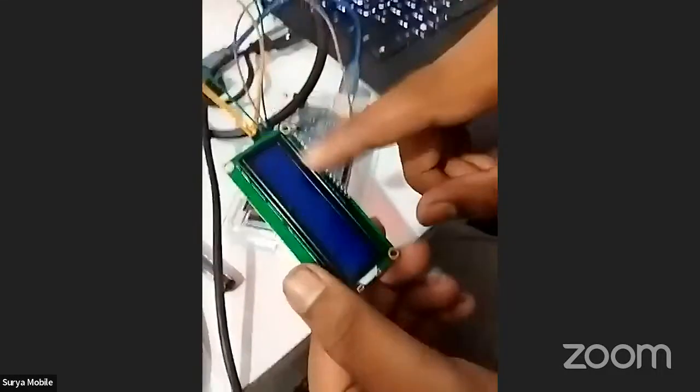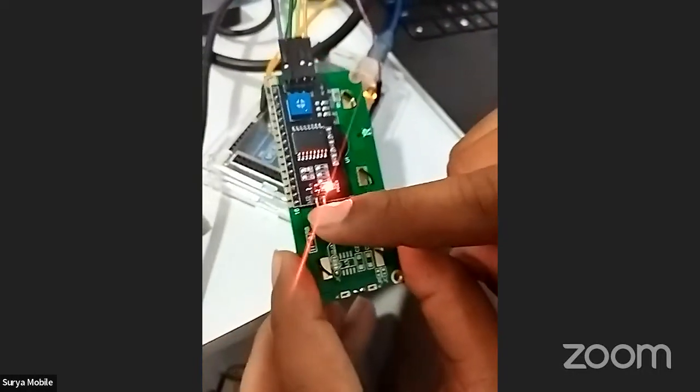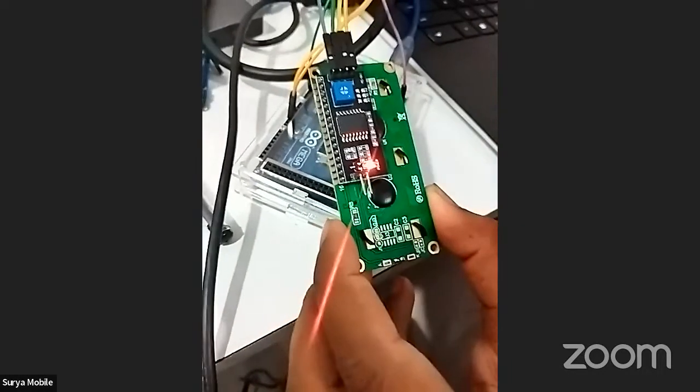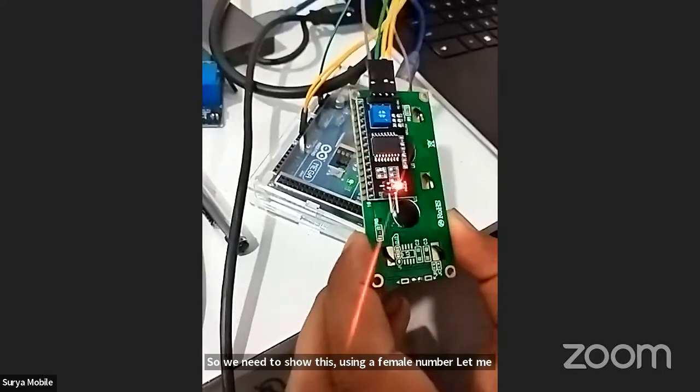So here we have done the connection, but you see there is no background LED because there is a terminal left. We need to short this terminal using a female to female jumper. So let me take the female to female jumper.